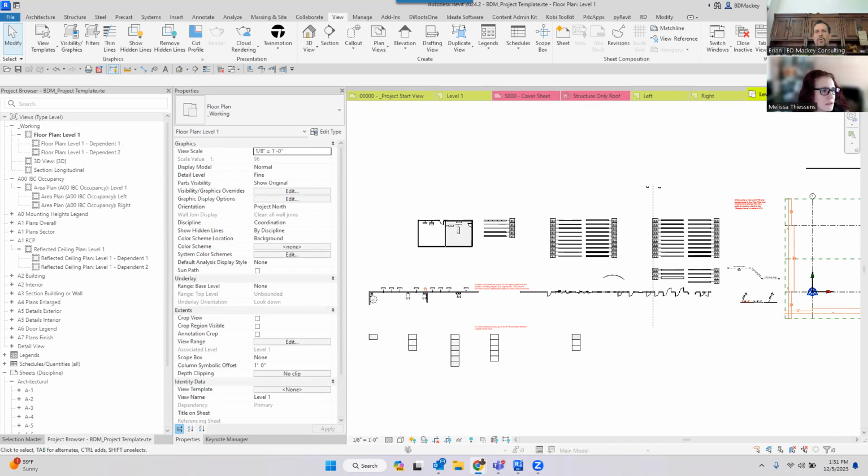It depends on how you want to set the project up and how the entire team is looking. Usually linked models are going to be set to overlay. And the reason for that is, let's say I set my structural model up to be attachment, and then my structural engineer opens up my model. He's going to get a circular chain of references because he can't link his own model into himself.